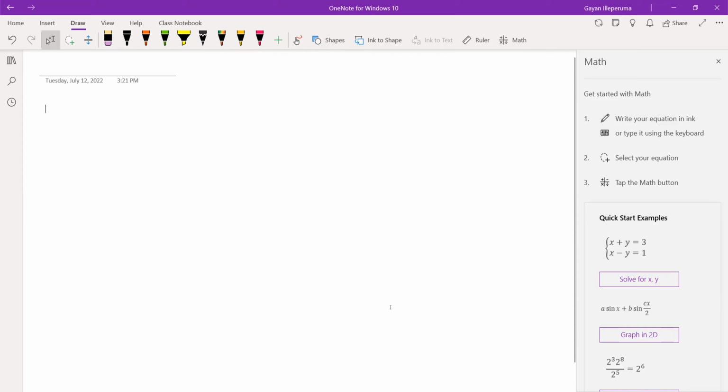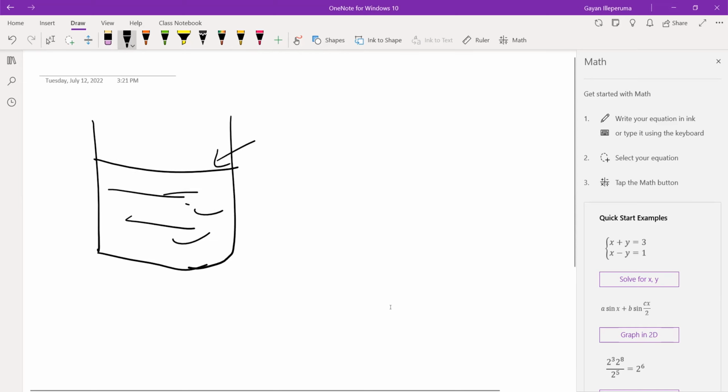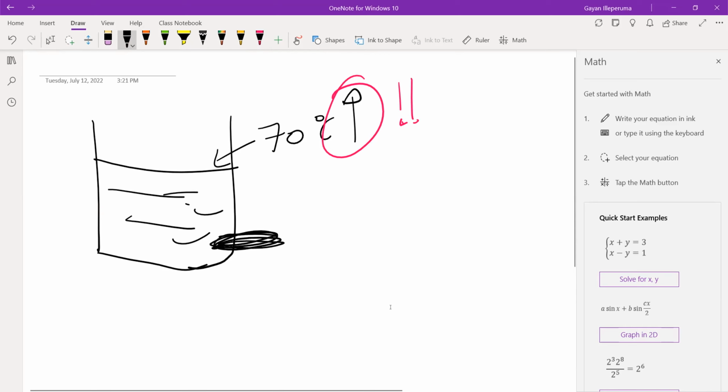he's manufacturing something at their home. Maybe in this hard time, he's trying to manufacture soap at home. Right? So you have to make sure the soap mixture doesn't get above 70 Celsius, or something like that. If it goes above 70 Celsius, then you have to run an alarm. I haven't touched on temperature sensors so far, but assume you have a thermocouple or something like that.